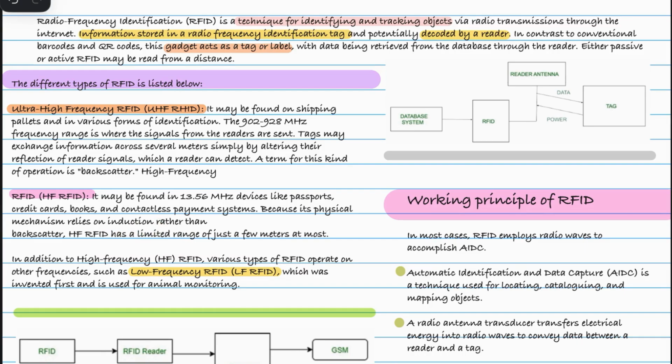So the reader and the tag must act like a split transformer over a short distance, like a few centimeters. NFC is simply a specialized sub-branch that restricts communication to an ultra close range, usually under 4 cm, offering highly secure point-to-point data exchange for contactless mobile payments.